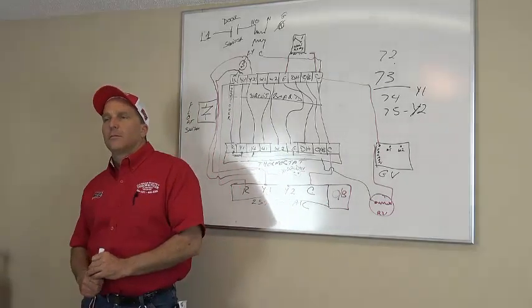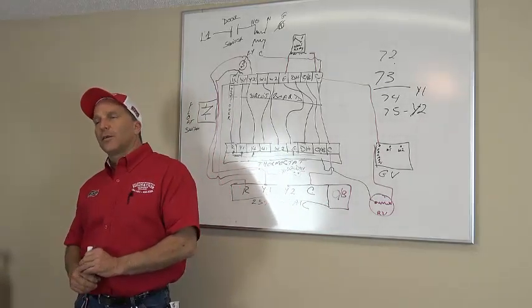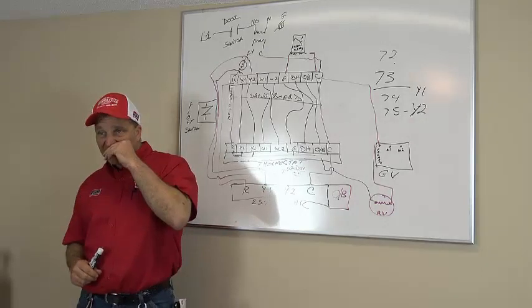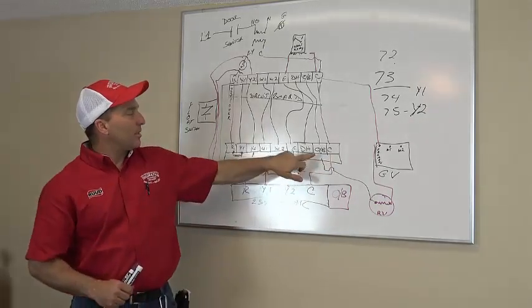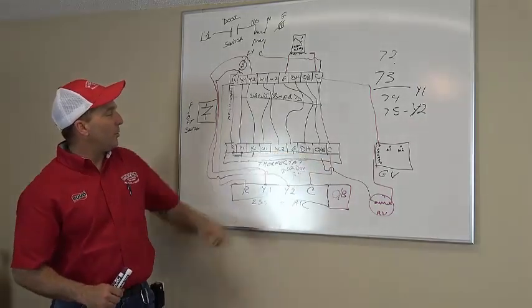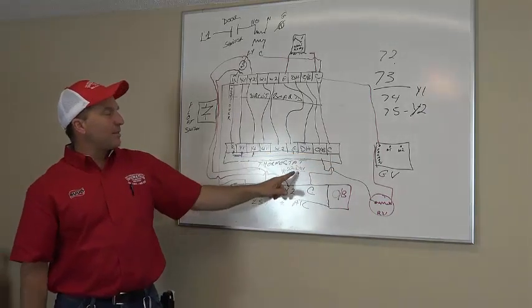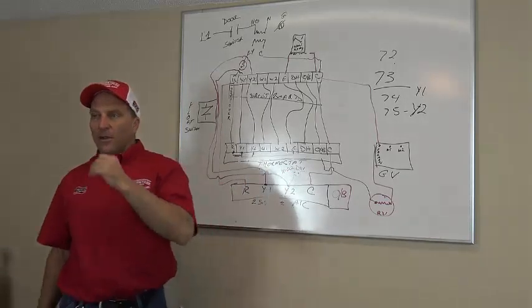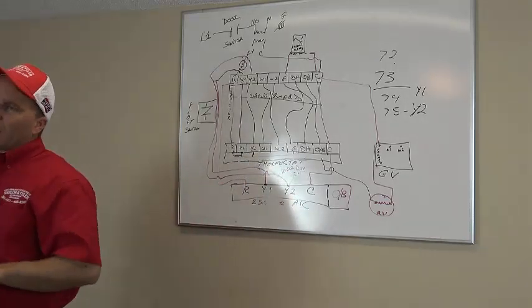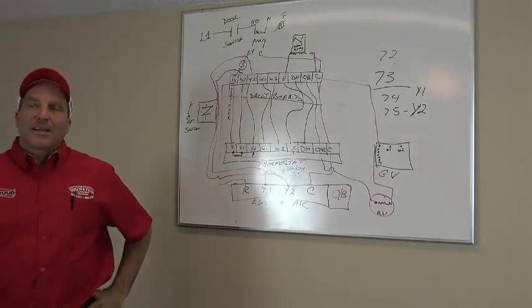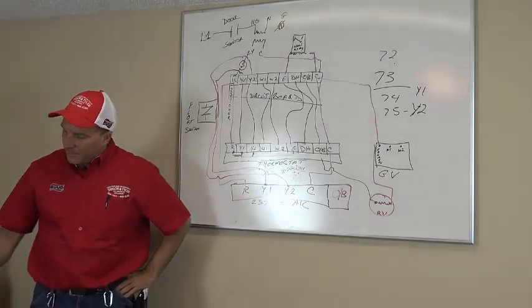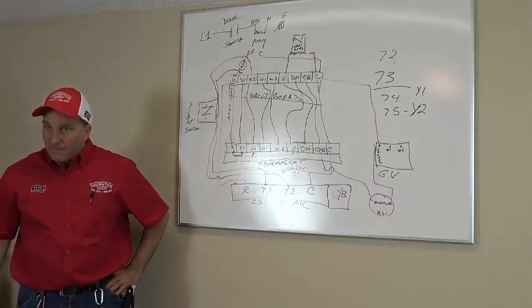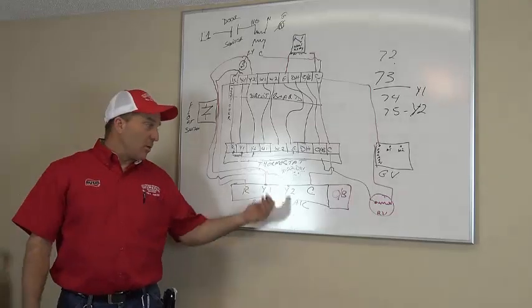And you trying to put it in heat? No, running the air conditioner. So my heat pump is not energized. Only G, Y1, and Y2 are getting energized. But I'm not sending voltage. That circuit board is not sending voltage to my solenoid valve to energize the solenoid valve inside that compressor so that the second stage kicks in. So the second stage won't ever come on. Right. So it just keeps running the Y1.